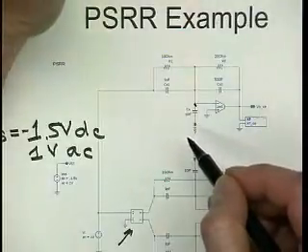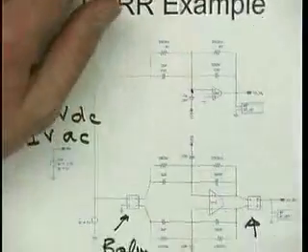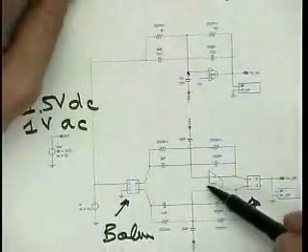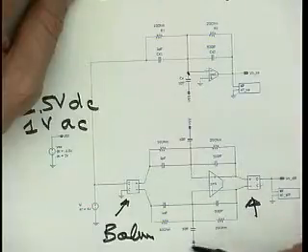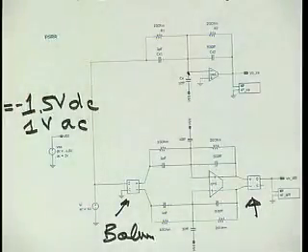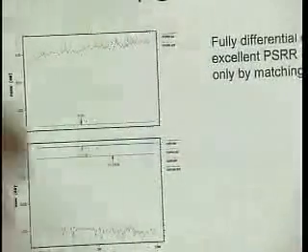A little bit of wiring or so. I mean, 10 femtofarads, you get that quickly, right? Not unreasonable. I also put the 10 femtofarads at the input of this amplifier, but I put it on both strands, arguing that I really do a very symmetric layout, and consequently I get the same parasitics on both nodes. Okay. And then I run a power supply rejection ratio analysis.